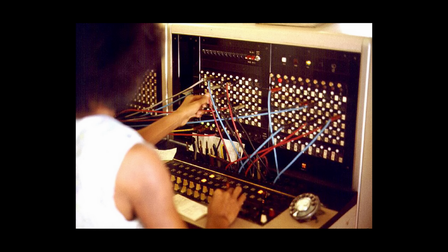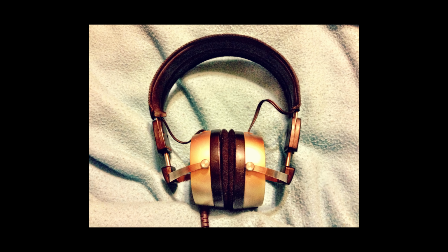It was originally invented for phone switchboards in the late 19th century, but is now most commonly used for headphones and audio equipment. It would not be applicable to use for a brain-computer interface application though, for a number of reasons. The first is that it is too long, even with the shortest being about 1 centimeter in length. We are putting the device on the back of the head, so we do have roughly this depth to work with, but we have other issues as well.